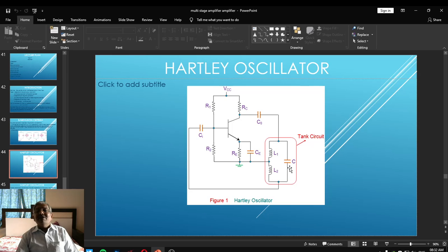That means lower terminal positive and upper terminal negative. When the magnetic flux fully collapses, the capacitor fully charges and the lower plate becomes positive, whereas the upper terminal becomes negative. This signal is given back to the input.